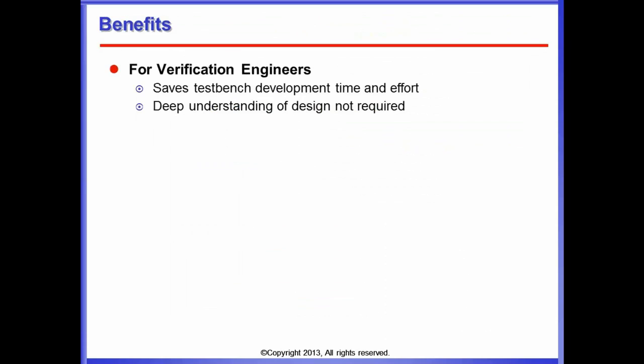So what that means is you cannot take this based on assumptions. You take a pretty high risk in getting an unstable design as soon as the reset scheme changes, as soon as the ratios of the clock change, as soon as the offset of the clocks change.